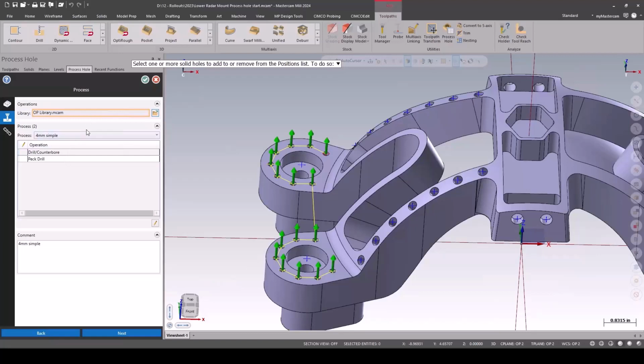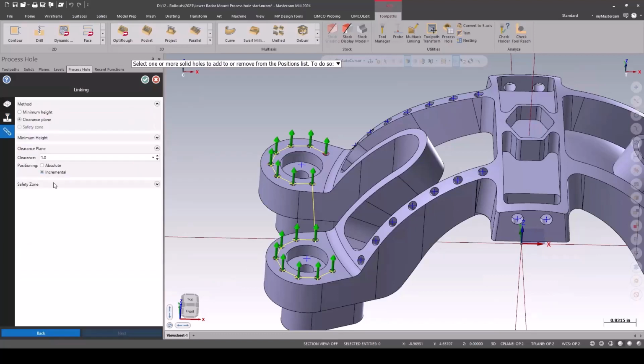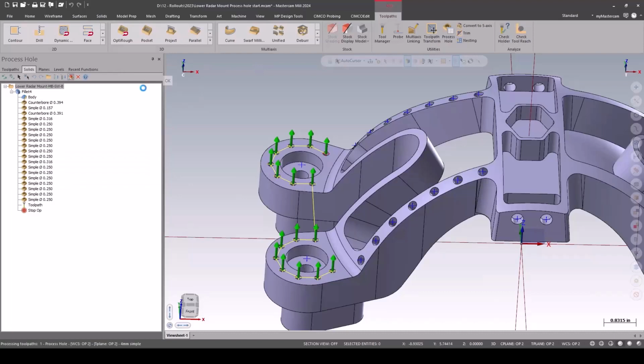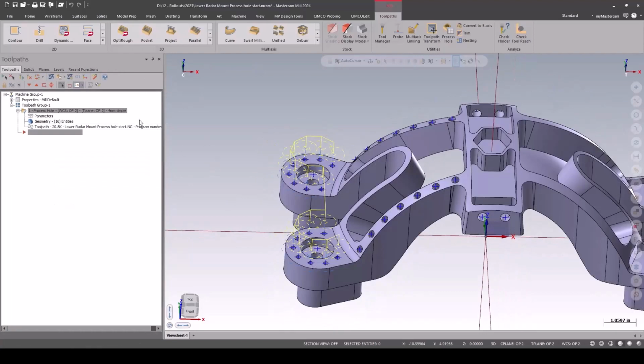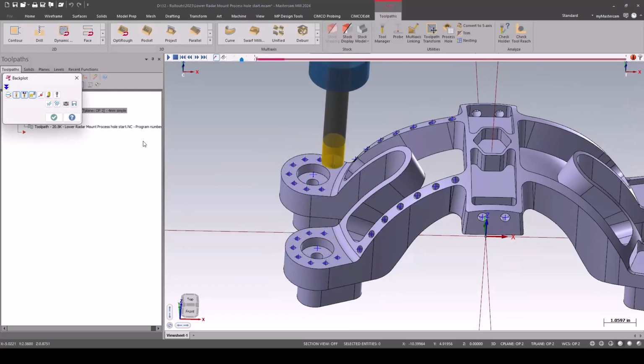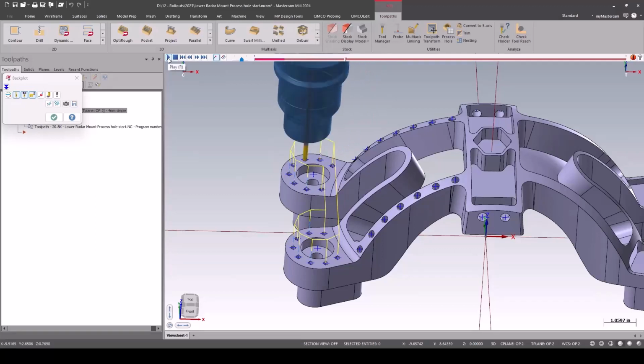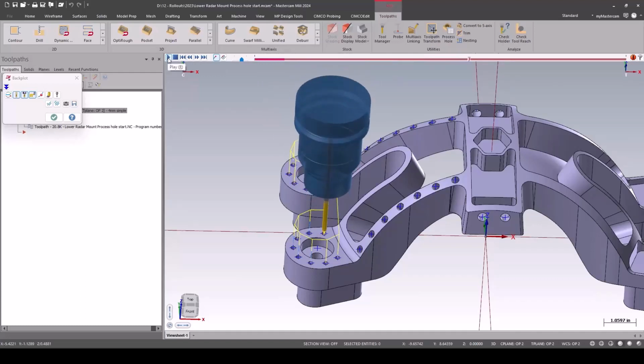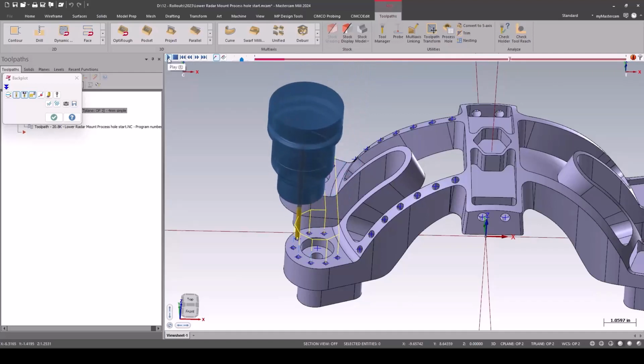The process is coming from a process library. We'll see what that does, but effectively, whatever the solid geometry feature said that hole needed to do, and whatever the process parameters say we do with holes like that, that's what's going to get done. So I've got a 3/4 inch spot drill, and then I'm just using a peck drill to finish cutting these all the way through. And any other options that I've set in my process parameters file are going to get reused. And you're basically just drilling a whole bunch of holes in a standard file and then saving that out.